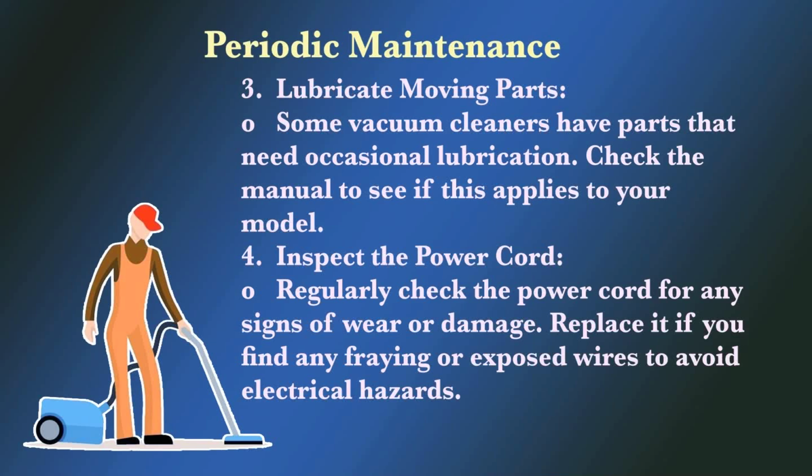Then number 4 is inspect the power cord. That is another point to be inspected. Regularly check the power cord for any sign of wear or damage. Replace it if you find any fraying or exposed wires, basically to avoid any kind of electrical hazards.